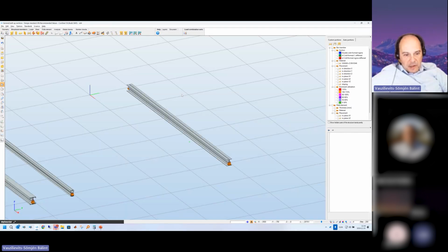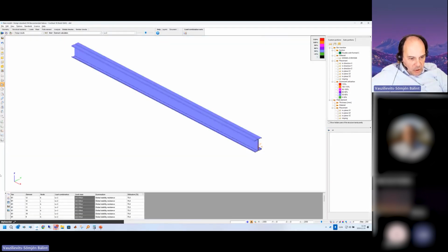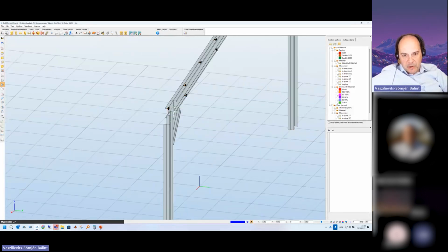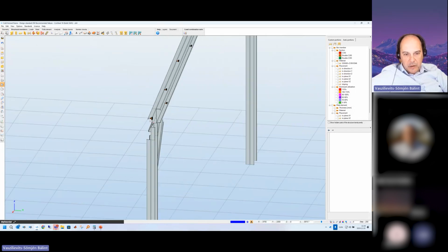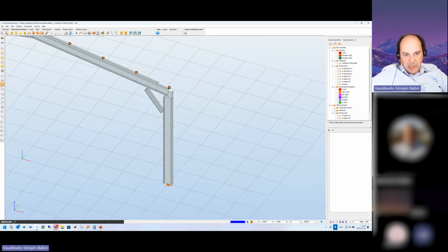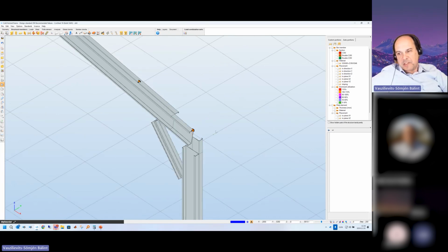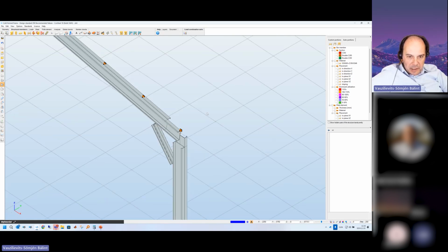And as a conclusion, I want to show something even more complicated. As I said, it's not just simple floor beams or columns that can be made from I sections, but also complex things such as a portal frame. Here, for example, without any spacing, two sections are used for the column and also for the rafter. And usually for these types of structures, what is very critical is the knee region. In a portal frame, typically this is a region which is exposed to bending moments.